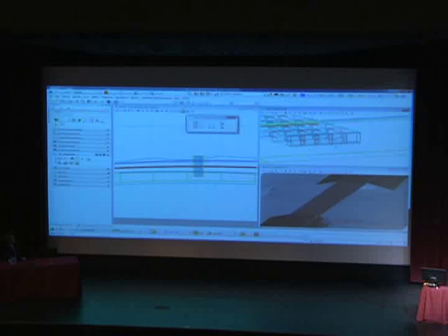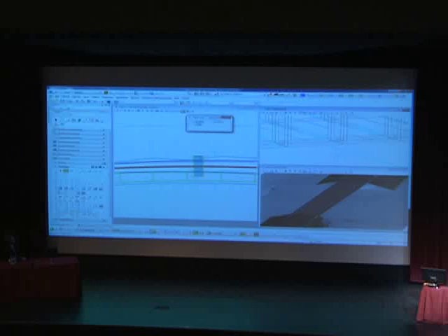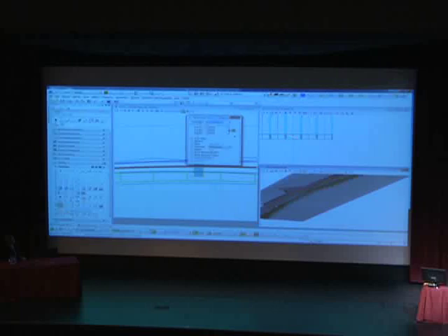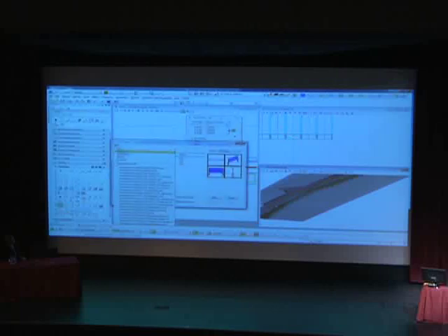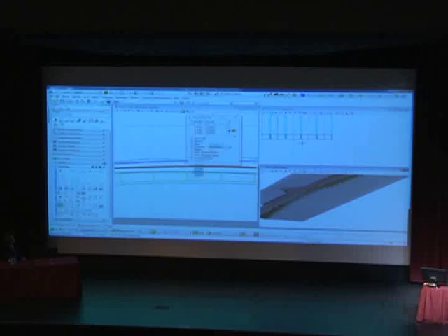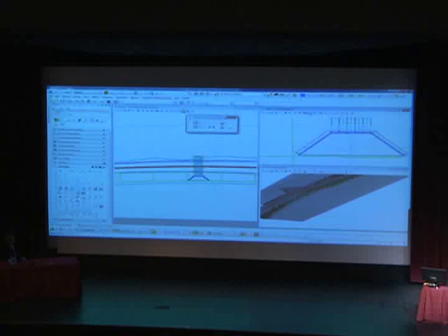All right, so that's just a multiple box culvert that I dropped on top of that line, and now you can see it's here. What I next got to do is put in a head wall and make sure everything ties in correctly. So what I went ahead and did was I created a cell, and eventually I see us having a library of 3D cells that we could use. In this case, though, I didn't have the library, so I tried creating one on the fly. And I'm going to go ahead and import that cell. These lines that I drew up here are just key points that I know, if I'm going to place my cell, I need to snap to these locations. I drew them in my 3D view so that it's easier to snap. It's best to draw it that way. So I'm just snapping to the two locations, and then the head wall pops in.